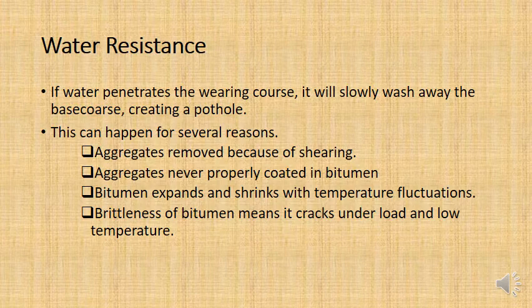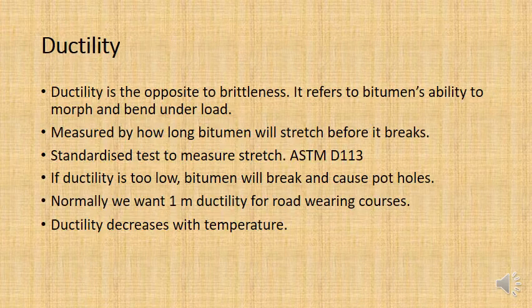Basically the bitumen can become brittle and crack at a low temperature, or it could become very liquid and wash away in high temperature. Both of those will mean that water can then penetrate into the wearing course. It breaks down the waterproofness of the wearing course.